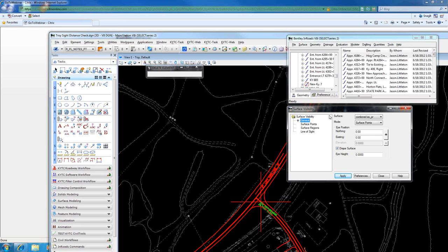And these are also very sensitive to crossing a surface boundary. I've found some issues where, like, if the sight line is shooting underneath of a disconnected surface or something, it freaks it out. So just be careful that you've got coverage for the whole area that you're trying to analyze, and that you've got one continuous surface that you're using.